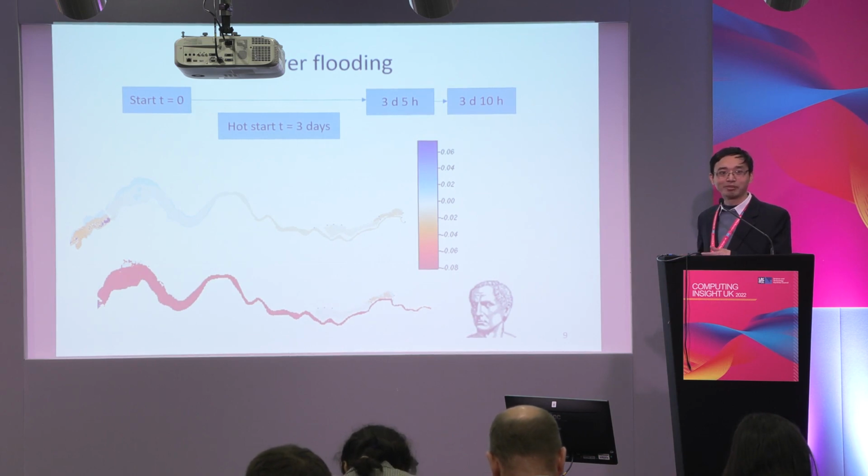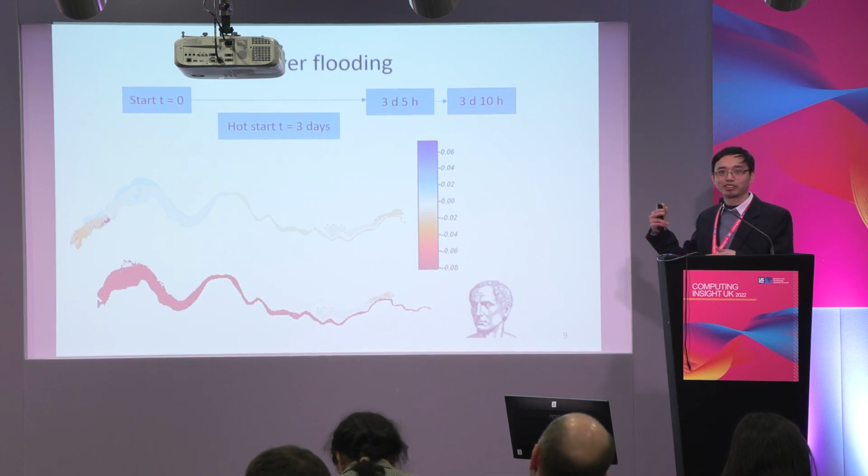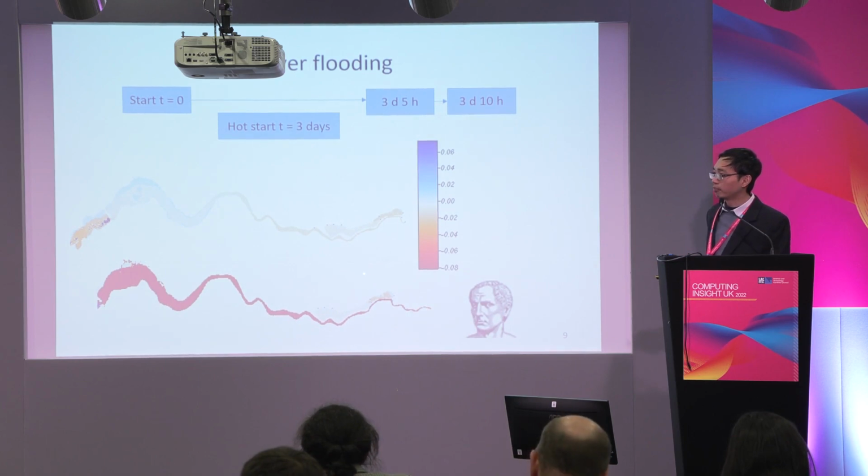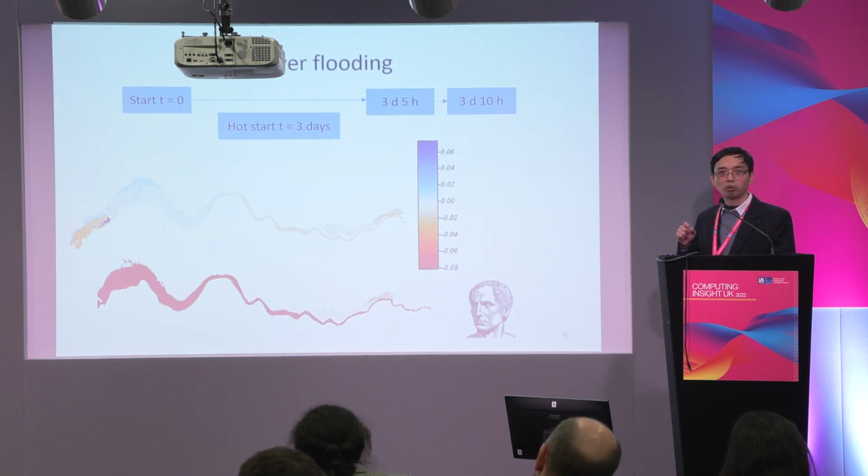We cannot reach a completely steady flow, and also our flooding condition changes every time. So again, it depends on the project we are working on. If the project involves long-term flows, for example seasonal flows, then we can compare the flow hydrograph produced, and see if the water level does not change much over time. Okay, so we stop here and save it as a hot start file. Later we can restart it for a new flooding event, for example.